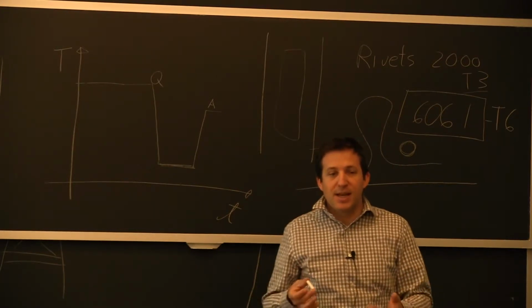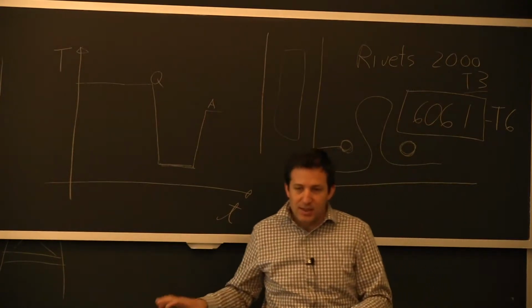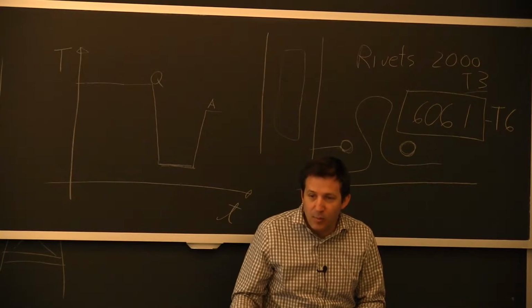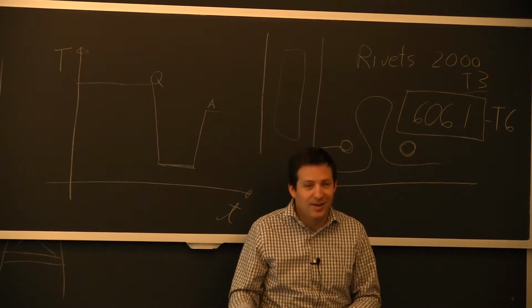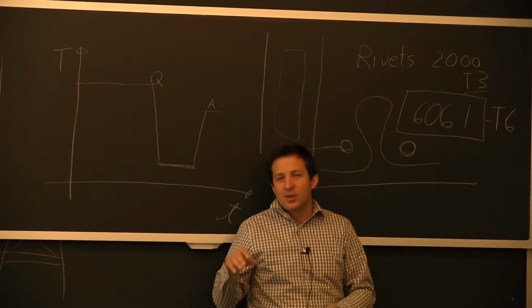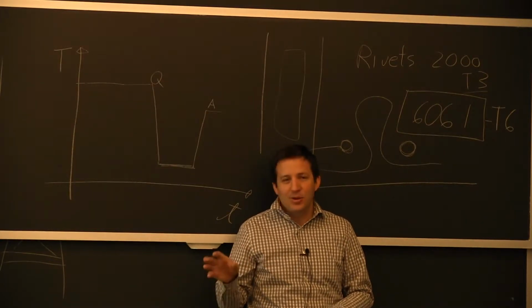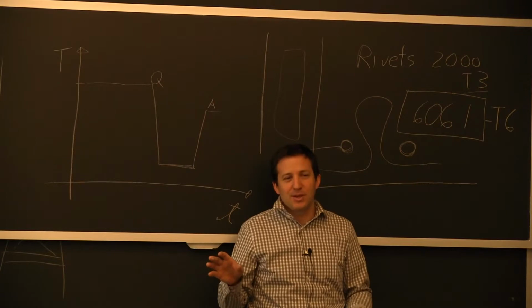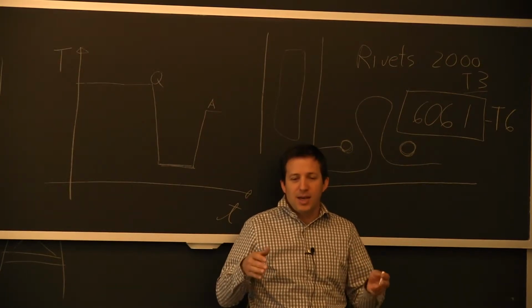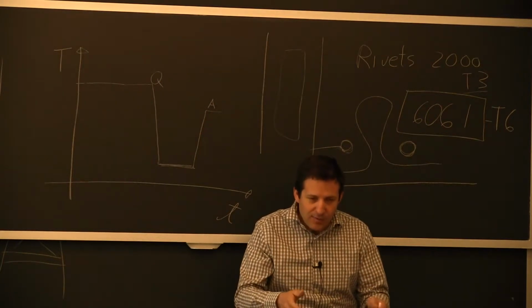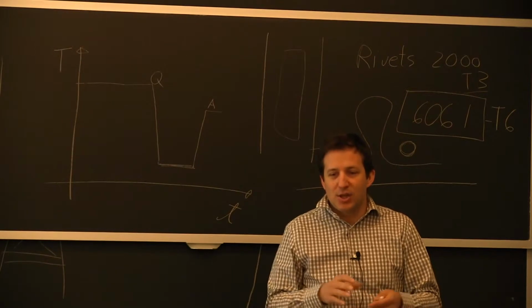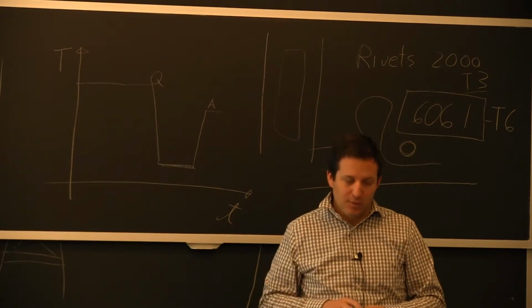So understanding the basis behind these factors of safety is something that, honestly, I've seen a lot of practicing engineers that have been there for a while. They see a factor of safety of 2. They think they're good. They really think that someone can go out and take 30% of it and get away with it. But we don't know. It could very well be that it's only 5, 10, 20% stronger than it needs to be, because it's just about the way it's calculated.